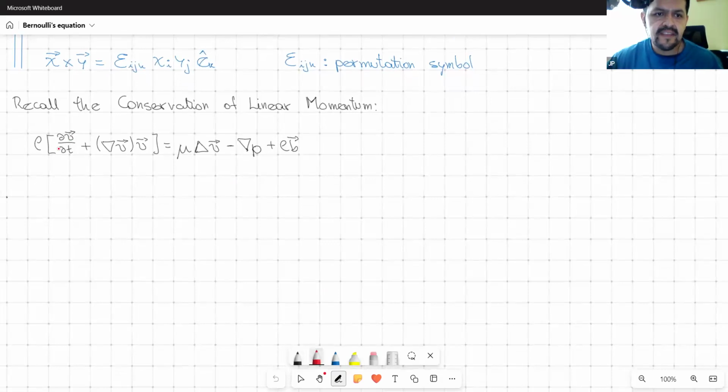Remember that we said that this was a steady state problem. So here we have 0. There's no viscosity, so this one is 0 as well. And we also say that this is basically given by negative rho g times the unit vector in the third direction. Assuming, of course, that the horizontal plane contains the 1 and 2 directions, the first and the second directions, and the third direction is perpendicular, vertical, normal to that plane.